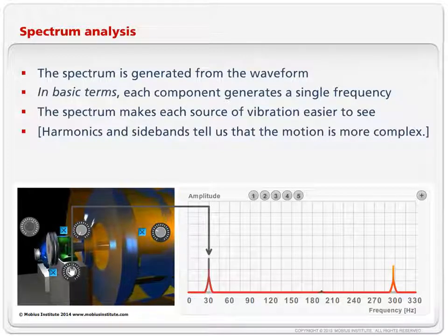But anyway, if I take one measurement and then I come back 30 days later and it's like this, 60 days later it's like this, I can say, okay, the unbalance is growing. And I can decide whether I want to do something about this high level of vibration. Do I think this is going to cause the machine to fail, the structure to fail? Is it creating noise that's creating a quality problem or a noise issue for workers and whatever?